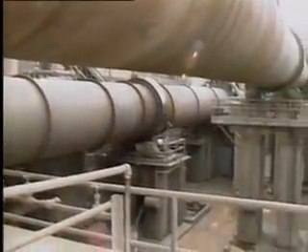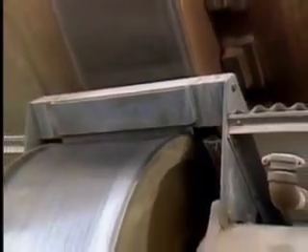The high kiln temperature makes the rollers hot. This heat and the kiln's weight would quickly melt and wipe away ordinary grease. This graphite lubricant is in the form of a solid block. Because it's a solid, there's no danger of its melting away and leaving the metal surfaces unprotected.